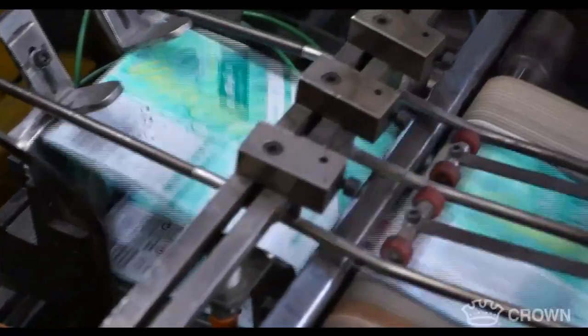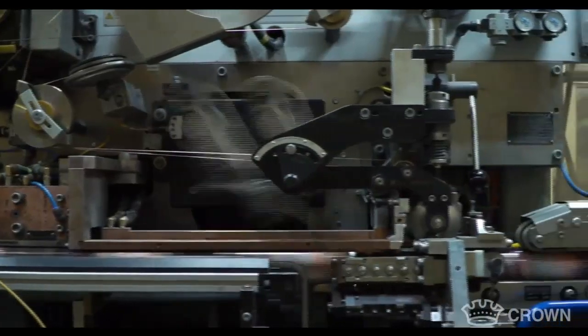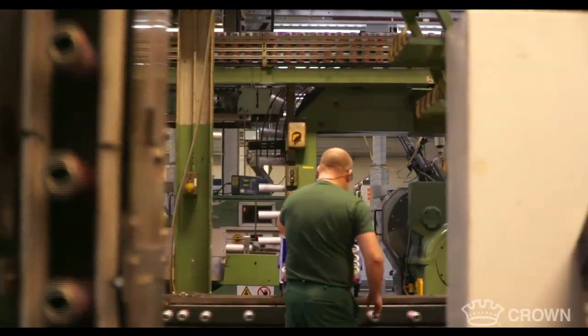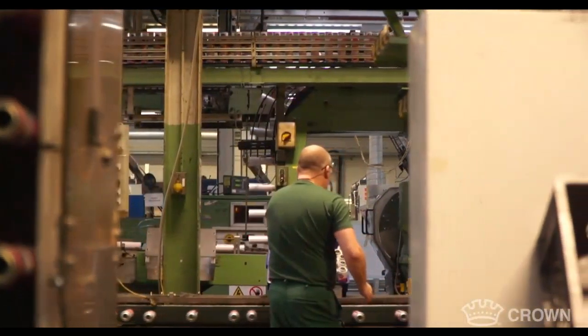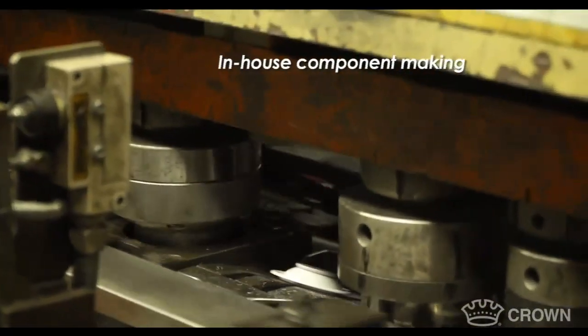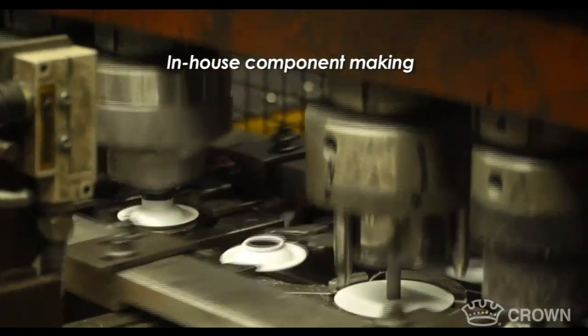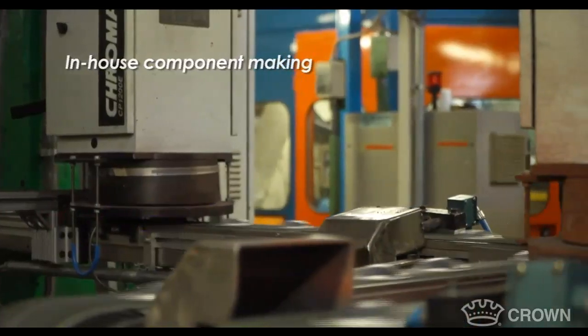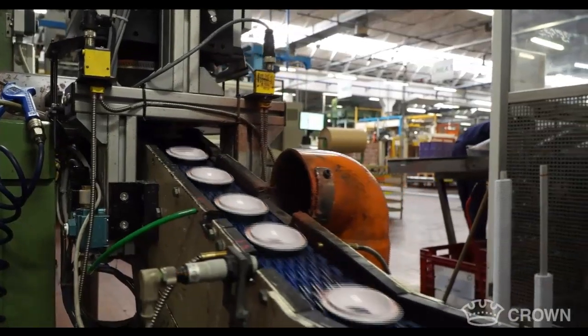Then you see that steel starts to get cut up into smaller strips of material and starts to get rolled and formed into the shape of the actual aerosol can. So now you have the cylinder body of the can. You've got some blanking going on here for the lids. That's called a cupping action as we go on. So all of these lids then continue to move down.